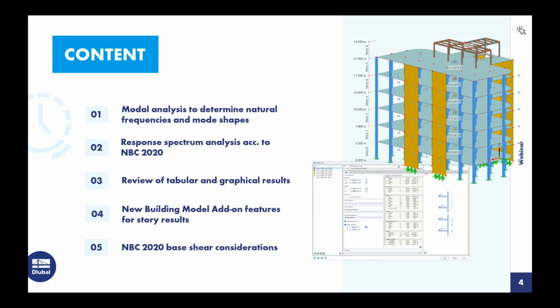So as far as the content over the next hour today, we will begin with a modal analysis of the structure shown over here on the right-hand side to determine the natural frequencies and mode shapes. We'll then move on to a response spectrum analysis, and in particular, according to the NBC 2020. For both the modal and the response spectrum analysis, we will review the results both in graphical and tabular form.